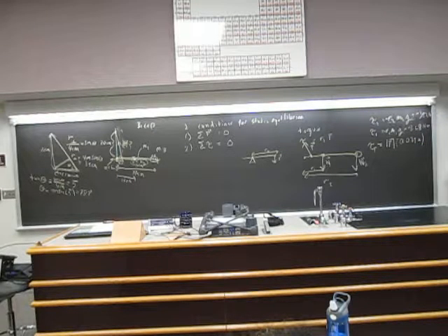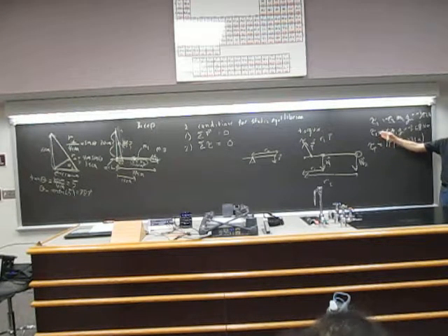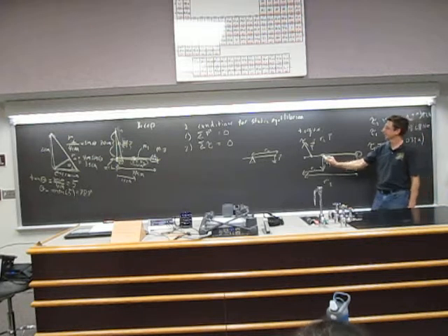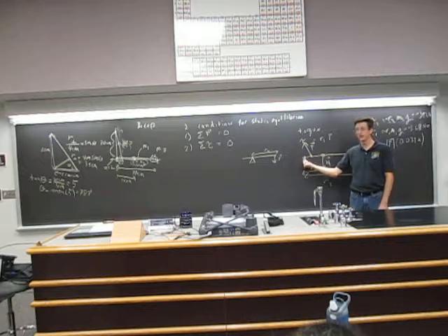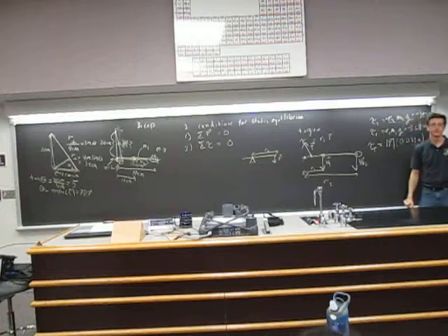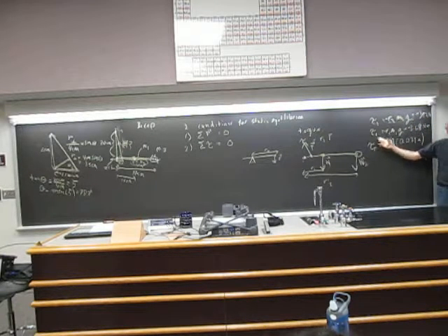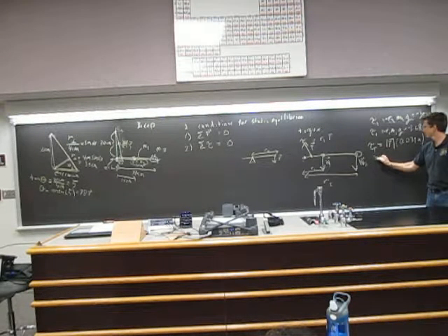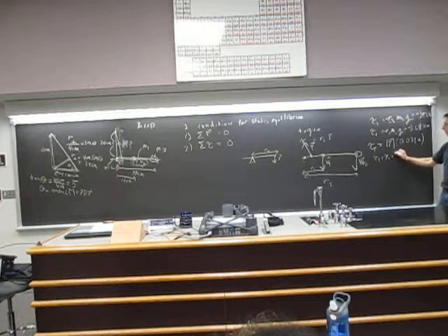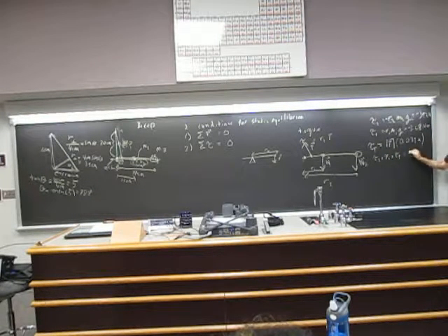All right, now if this thing's supposed to be in equilibrium, what are the forces on it? By the way, there's also force on the elbow. Would that exert any torque? Because R perpendicular is 0 since it's at the pivot, there's no torque with that. So if I wanted to sum up the torques, what should the result be? 0. So torque 2 plus torque 1 plus the torque due to the tension is 0. That's the condition for equilibrium, that I'm able to hold that.